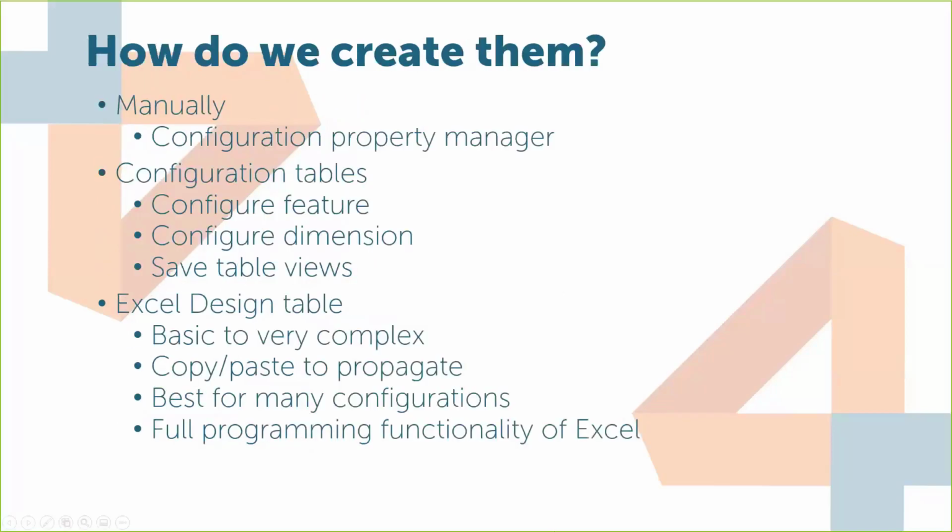So how do we build these configurations? Again, manually. I'll go through a quick example leveraging the Configuration PropertyManager. I'll talk about, again, configure features. Right-click on a feature, configure that feature, or right-click that dimension in the right-click menu. You'll see those pop up.